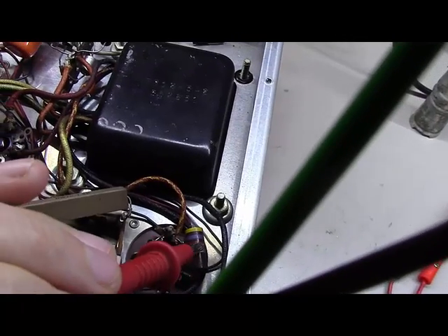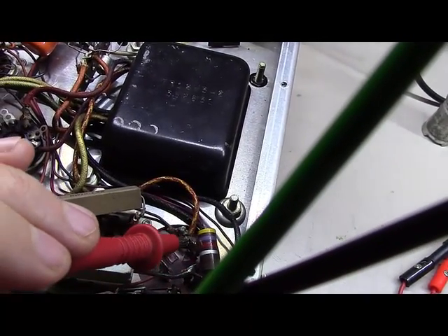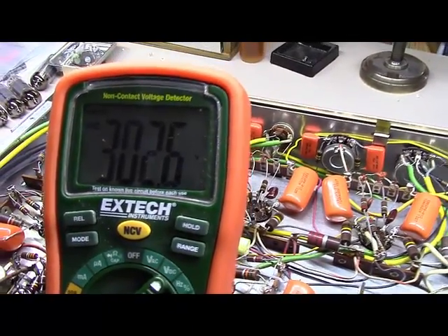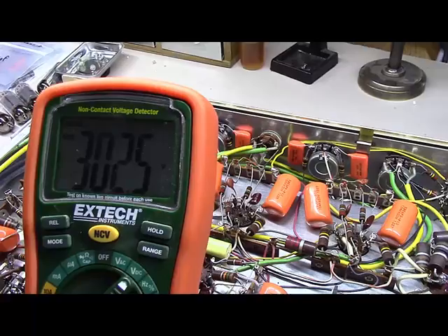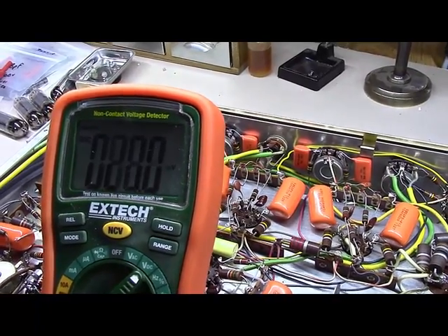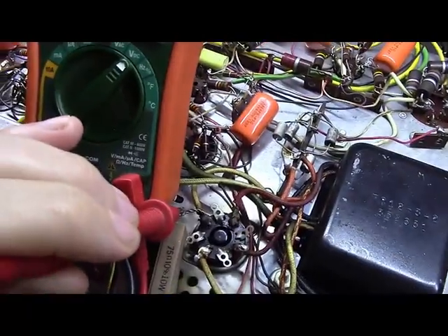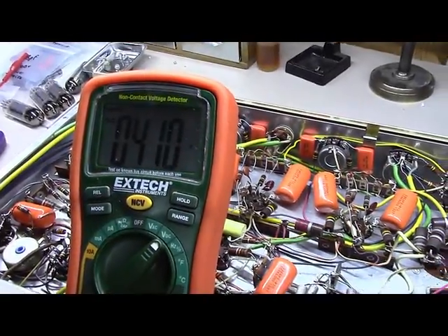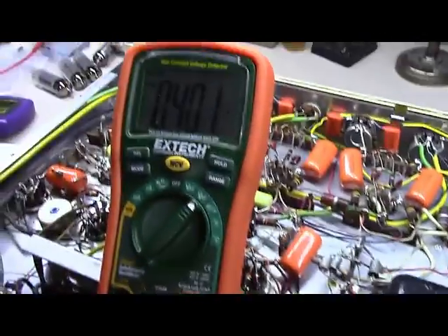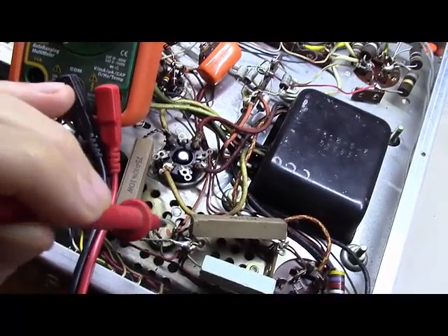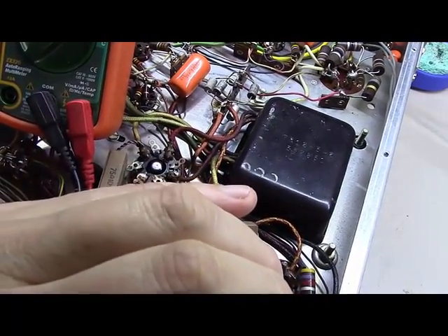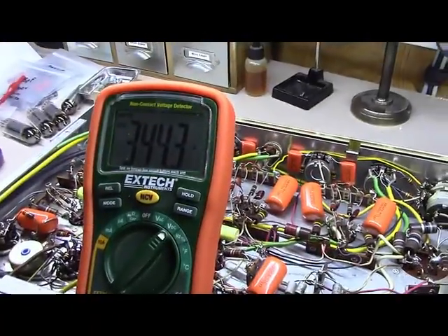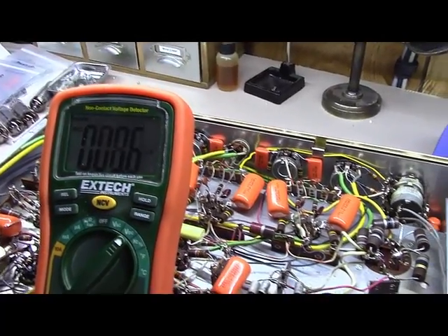Look here, there's another resistor. On the other side of that resistor, if I go touch it, I'm down to 302 volts. So as you can see, the way this power supply is working is it's coming off the main piece here with a higher voltage, 411, dropping down here to 401 at this point. Come to the other side of that, there's another resistor here. Get that, 343. Go to the other side of this little resistor right here, down to 303.